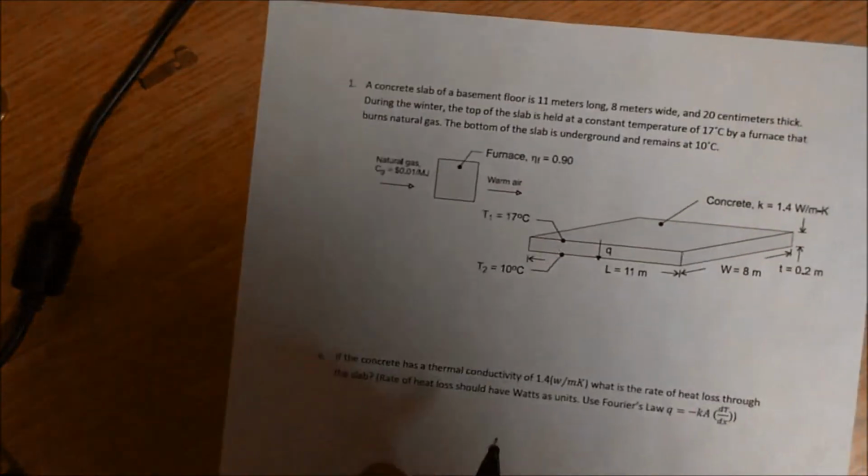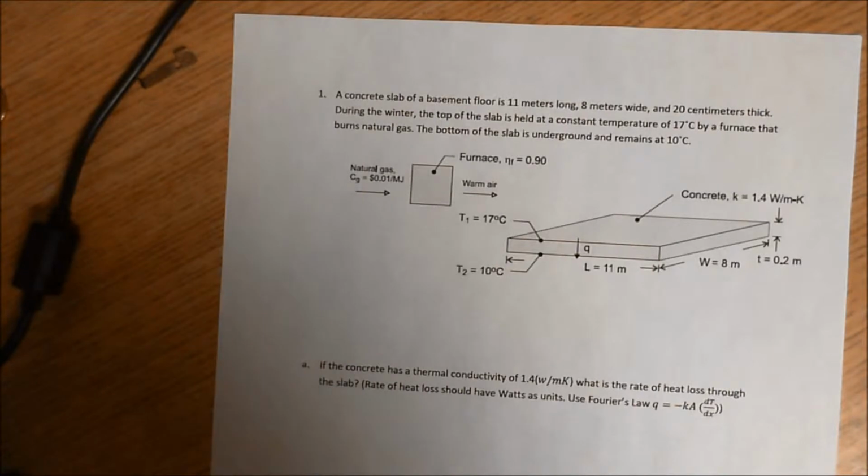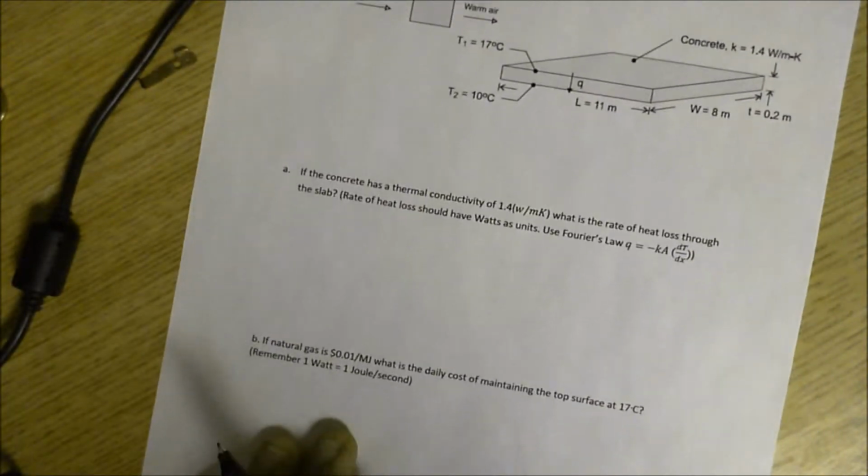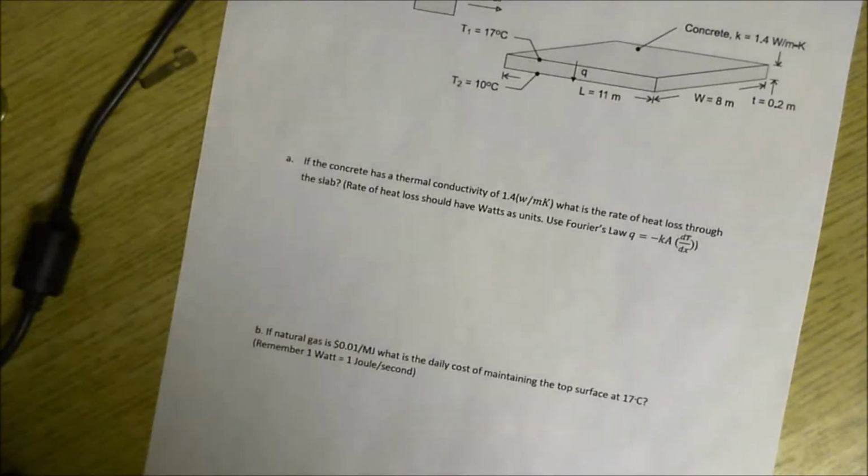So our problem states that a concrete slab of a basement floor is 11 meters long, 8 meters wide, and 20 centimeters thick. During winter, the top of the slab is held at a constant temperature of 17 degrees Celsius by a furnace that burns natural gas. The bottom of the slab is underground and remains at 10 degrees Celsius. So we are asked to find the rate of heat loss through the slab, given that the thermal conductivity is 1.4,